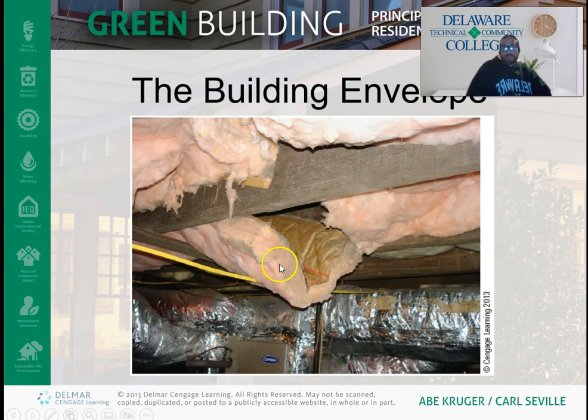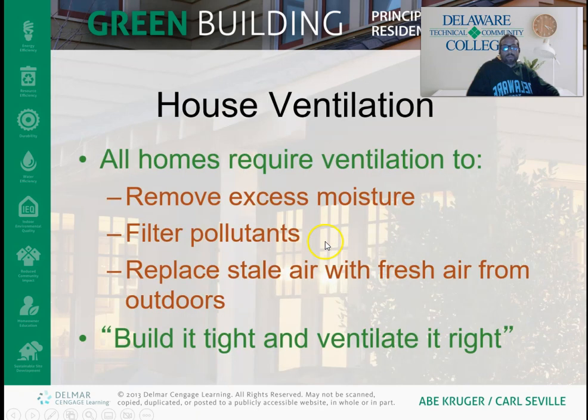But you can see there's a little break in the building envelope here because there's some drooping insulation, which means the thermal and air barrier aren't continuous and in contact. That insulation should be consistent and constant throughout the entire envelope. If you have a little hole or gap, that can really compromise your insulating value.